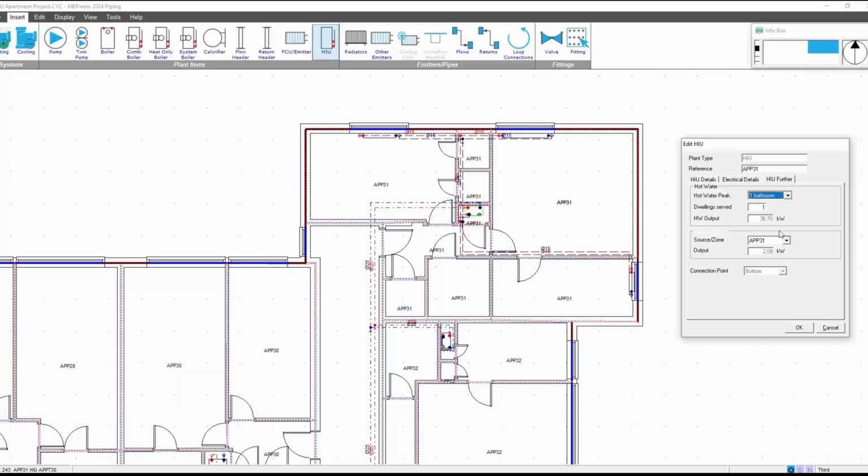Same applies with the space heating. You can apply the space heating on a zonal basis, as is the case here. You can apply the space heating on an entered load, which you can enter by hand. You can enter from the codes of practice based on the number of bathrooms as above from tables, or you can actually use the connected load.